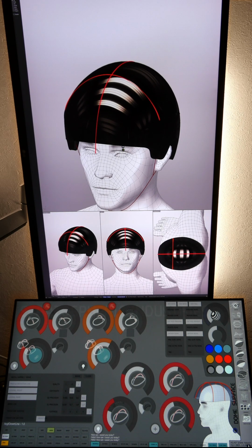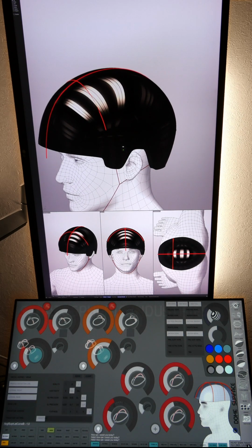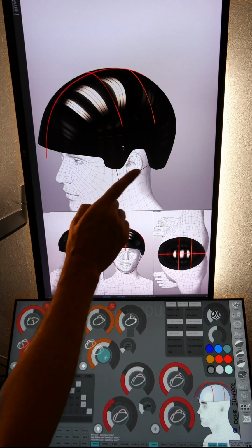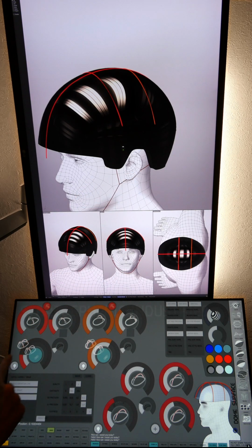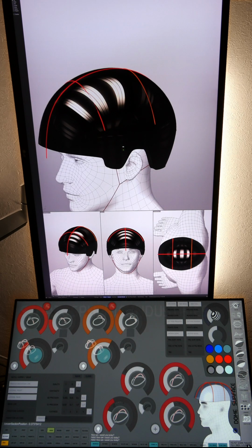We have a front defining curve and a rear defining curve. So this controls the latitudinal curvature of the helmet. This is the front curve, this is the back curve. This controls the placement along the shape. That moves it to the back. This moves it to the front, so you can have different control in the front. At certain points in time, the definition will break, but that's fairly rare. It always can be tuned up later.